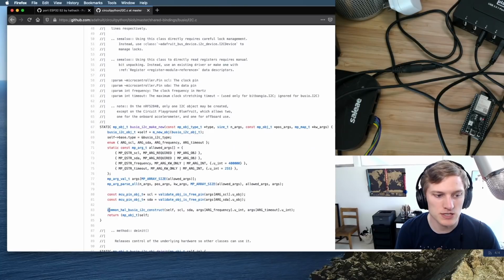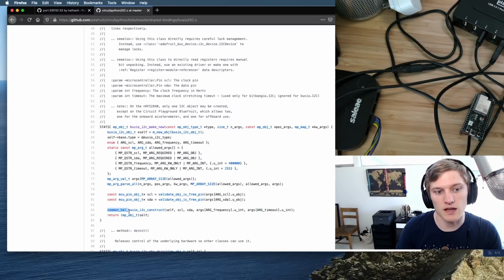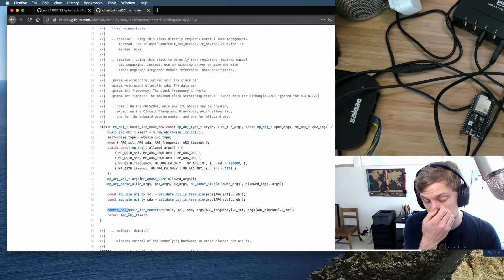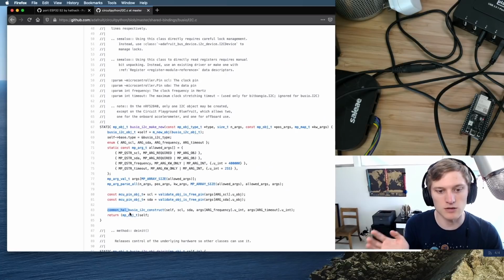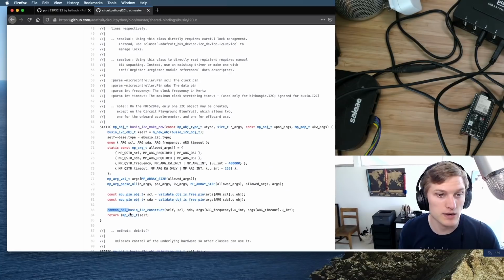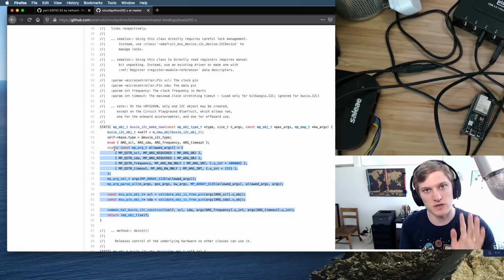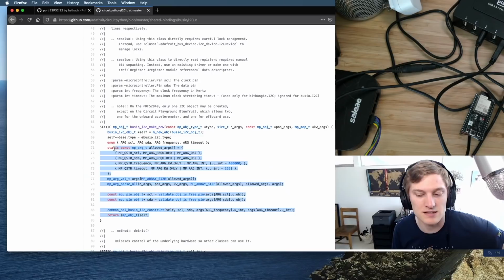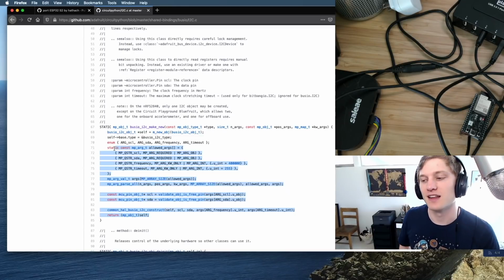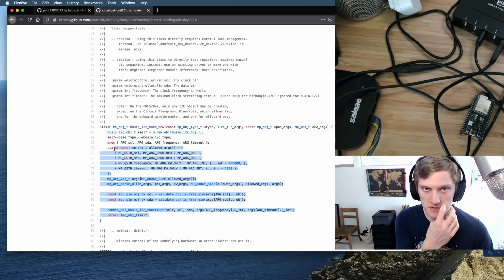And then in the implementation, we have these common_hal functions. These are C-level APIs that all the ports implement. So when we add I2C support to the ESP32-S2, we'll implement common_hal_busio_i2c_construct with those arguments, and then we'll call into the ESP-IDF later to make it actually happen. That means that all of this code between Python and C is shared, and it'll be identical, which is awesome. Because identical means that you can build drivers on top of it, and all those drivers work regardless of what platform you're on.